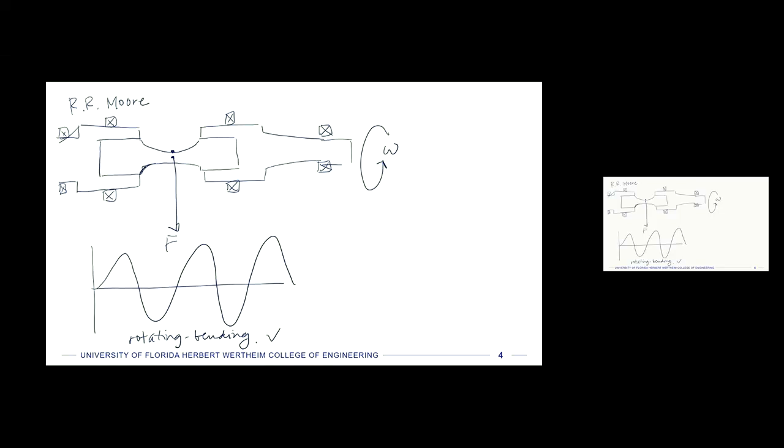You can also have a bending machine, or what's also called a flat plate machine. I'll draw that on the next slide, in which you take a flat plate, right? This is a side view. And you mount it into a fixture that's not going to move, so it's kind of clamped in. Then you put a driving clamp at the other end. This region that it occupies on the beam is very small compared to the length of the beam, so we can treat this as a Bernoulli beam.